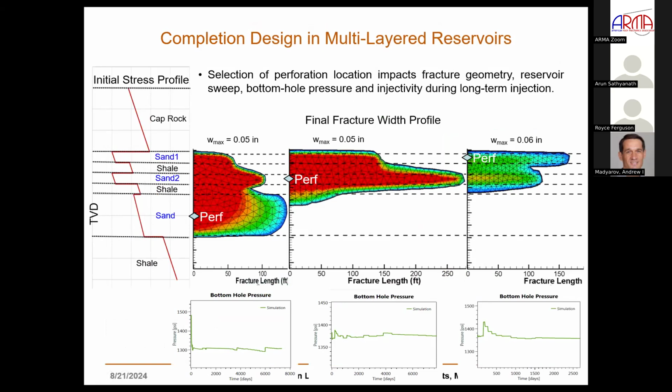And so what happens to the frac pack? Well, the sand or the gravel that's in the frac pack actually slumps down, and you lose sand control as a result of this. In other words, in the beginning, the frac pack is fully full of proppant, but then when you widen it, the sand actually settles down and you lose sand control. And as a result of that, you can actually get some significant fill up of the wellbore with sand. And this is something we've observed many, many times. And the ability to model that is actually really important.